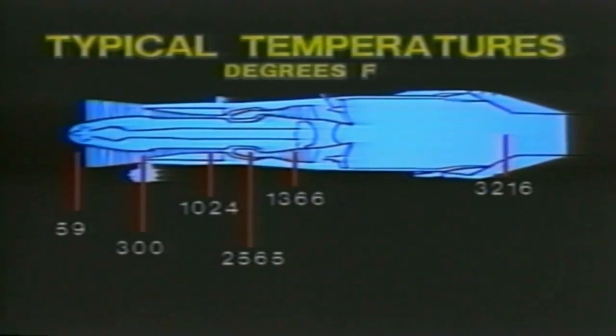Is it any wonder we're continually searching for the best in metals? And consider the exterior parts, the components, the wiring, the plumbing. This will give you an idea of what the trend of temperatures is on the outside of the engine. Cooler, sure, but now you know where the hottest places are and why they mount these exterior parts up around the compressor and diffuser sections, where it's not so darned hot.